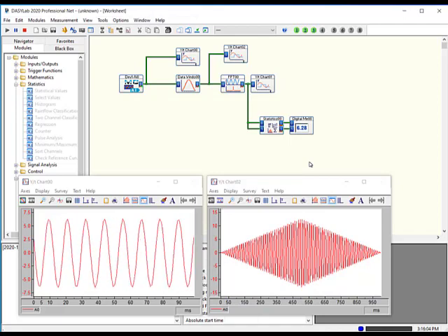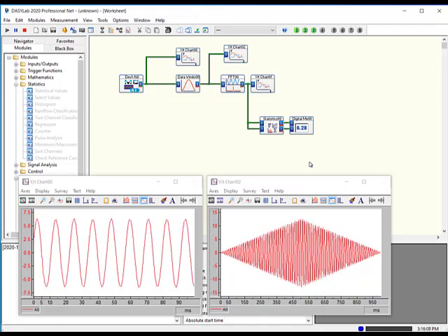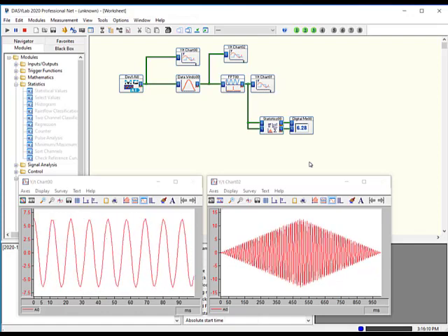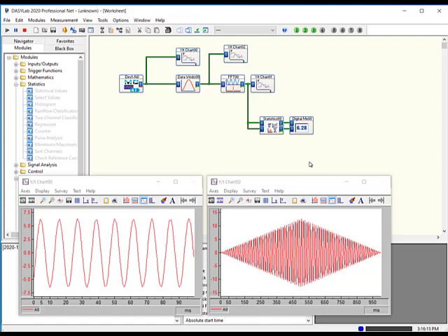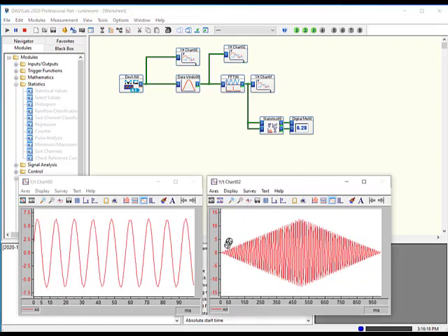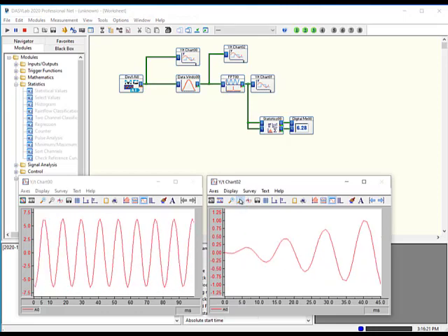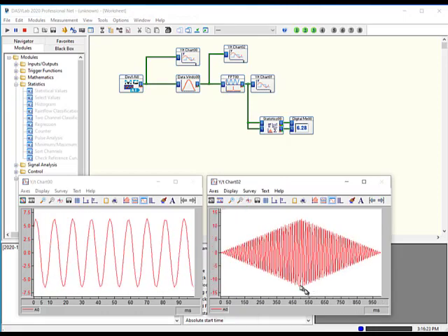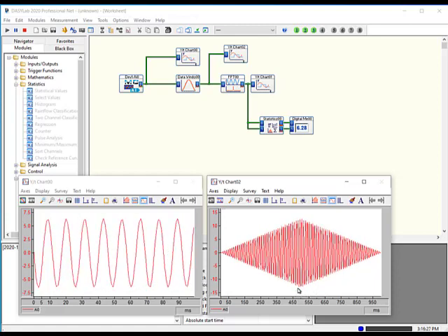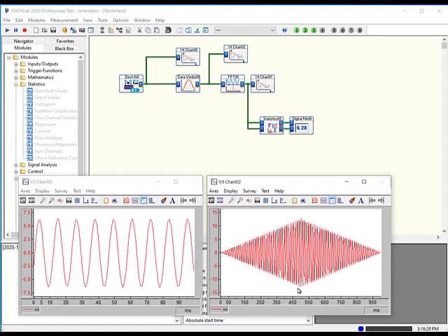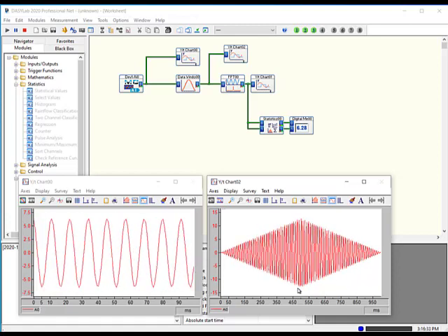So when you apply the Bartlett window, what it's going to do is it's going to weight the data at the beginning of the block and at the end of the block to minimize the effect of what might be partial cycles. And it will emphasize the amplitude in the center of the block to offset the weighting that you did at the beginning of the block. So the triangle is kind of clear.